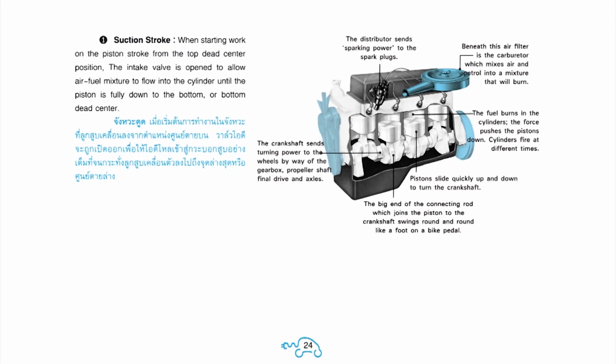1. Suction stroke. When starting work on the piston stroke from the top dead center position, the intake valve is opened to allow air-fuel mixture to flow into the cylinder until the piston is fully down to the bottom, or bottom dead center.